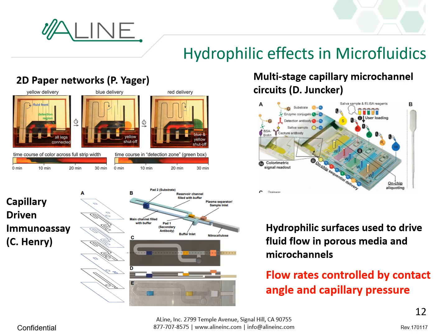An alternative method, which is a combination of the two methods, is the use of capillary-driven immunoassay (CADI) devices from the Henry Lab at Colorado State. This is a combination of a multi-layer channel laminate with hydrophilic properties and hydrophilic coatings together with a series of pads. So it's kind of a hybrid between the two approaches that really showed how the use of capillarity can allow you to drive fluid in a way that does not require external control. All of these examples use hydrophilic surfaces to drive the fluid flow in a porous medium and microchannel.